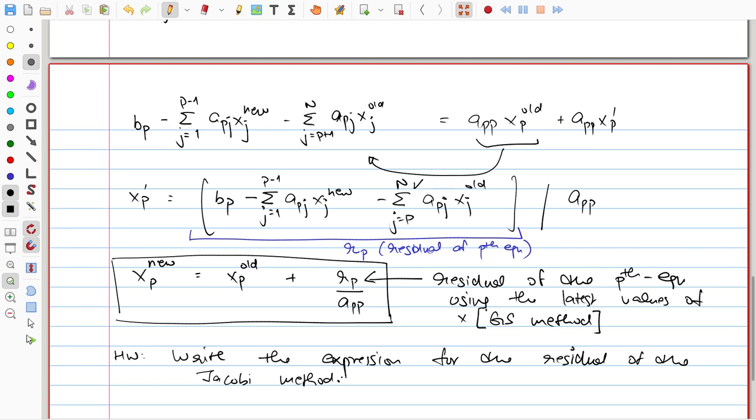And for those who have actually used ANSYS Fluent, that's one very popular commercial software for solving fluid mechanics CFD problems. When you run the code, while it's running, it will plot some graph. That graph is nothing but the value of residual versus iteration. And I have noticed that many times when we ask those who are doing research what is happening here, they say the value of residual is going down, so it's converging. Well, that is right, but what exactly is the residual and what is the meaning of iterations should be clear.